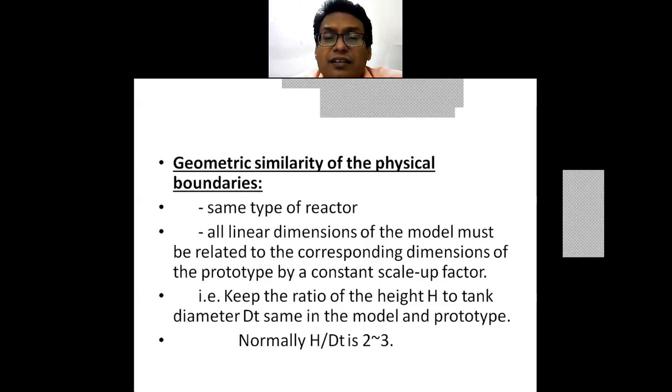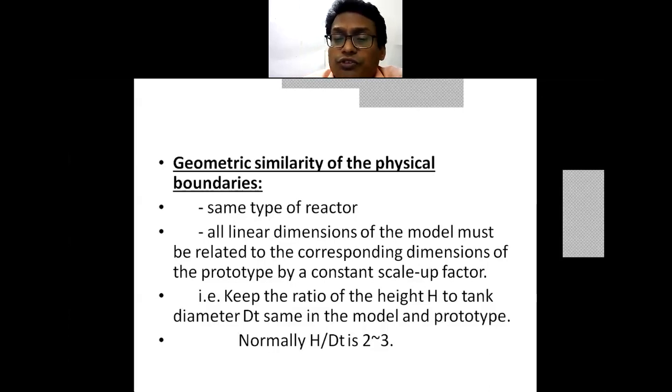This scale up factor will be helpful for correlating the smaller dimensions to the higher dimensions. That is, keep the ratio of the height to the tank diameter the same, h upon dt, kept constant, that is L upon D, or h upon dt. So length is nothing but your height. That corresponds to say 2 to 3.